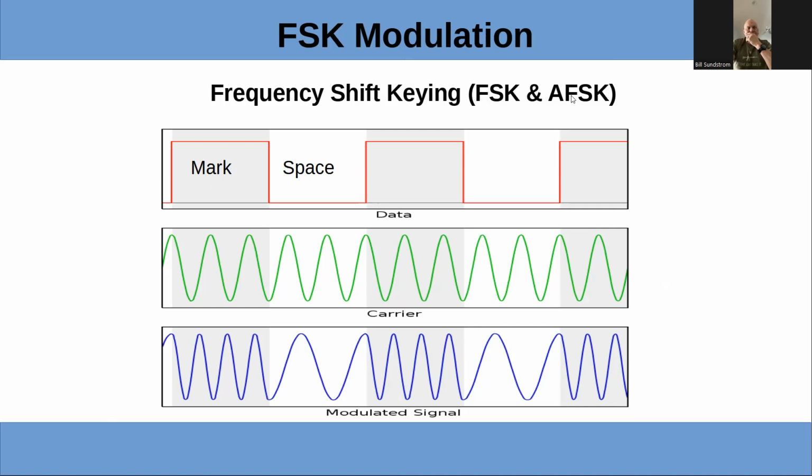The other one up here, audio frequency shift keying, is slightly different. And that's what modes like FT8 and FT4 and some of those, I'm not sure about JS8Call, but FT8, for instance, uses what they call audio frequency shift keying, where it will generate an audio signal.